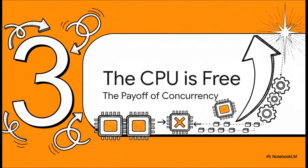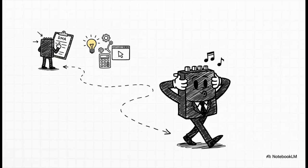And once that work order is handed off, we get to the real payoff of using DMA. We get to build a much more efficient system through something called concurrency. With just those 4 simple instructions, the CPU has told the DMA everything it needs to know. The CPU's part in this big data transfer is now basically done. It can go off and do something way more useful.